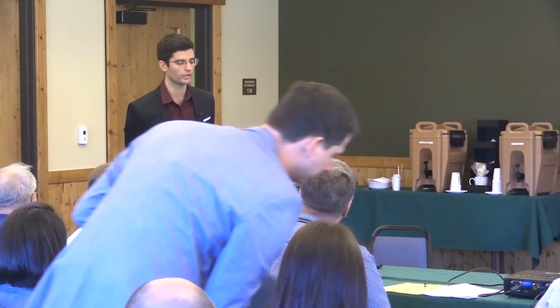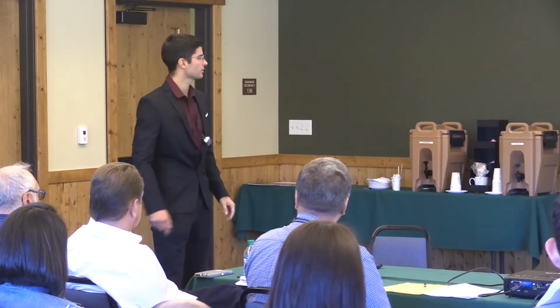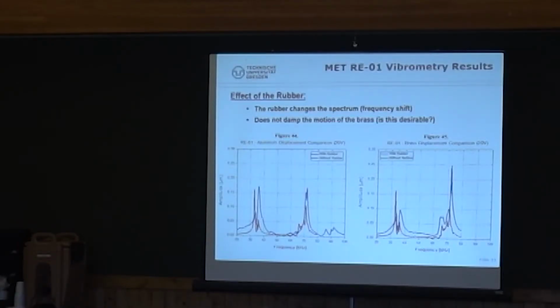This will be addressed when we do another experiment, which is coming up. I'm almost done. This was looking at the difference between having a rubber and not, because with our own thruster we can change things around. So we tested the vibration with a rubber and without a rubber. I still have to do the experiment that Jamie mentioned, looking at the bracket to make sure that the rubber decouples the motion of the brass from the bracket. Having a rubber or not doesn't change the amplitude that much, but it seems to shift the frequency.